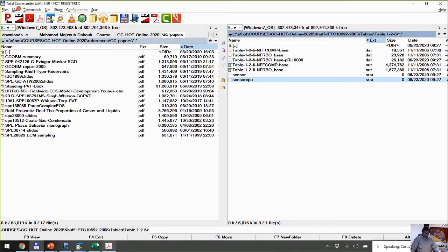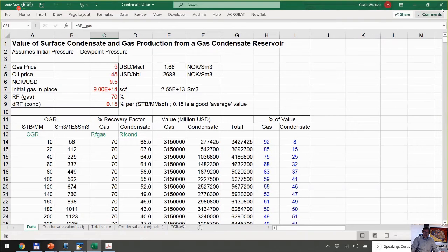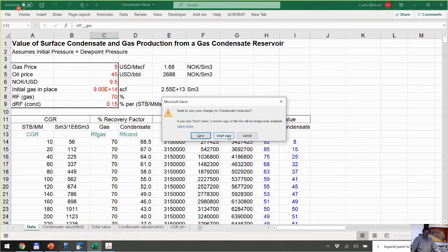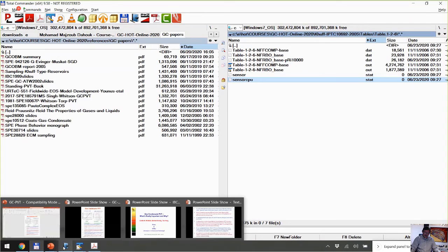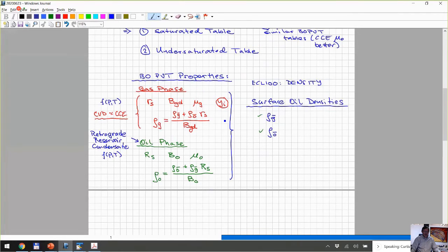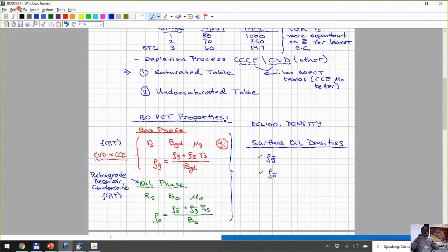Okay, but yeah, I don't generally recommend it, because if you're generating from the equation of state to begin with, you can give a maximum pressure for which it uses the equation of state. And I would much rather extrapolate with the equation of state, at least undersaturated properties.